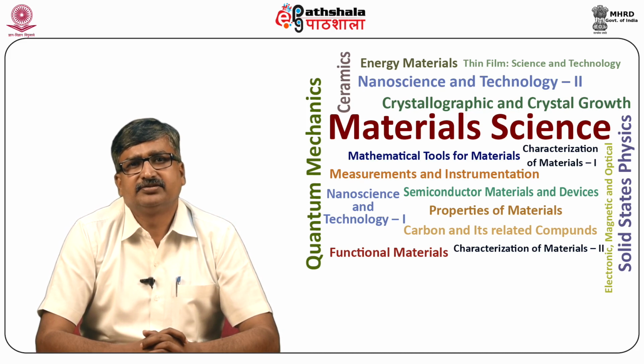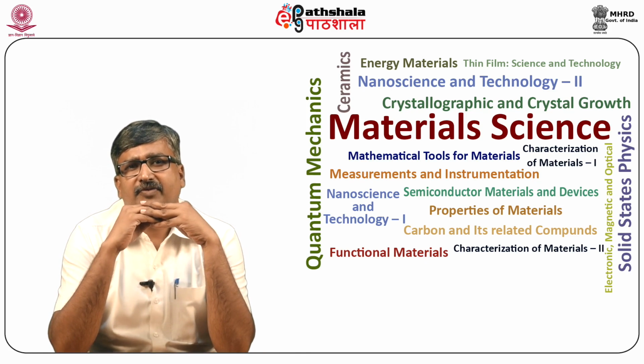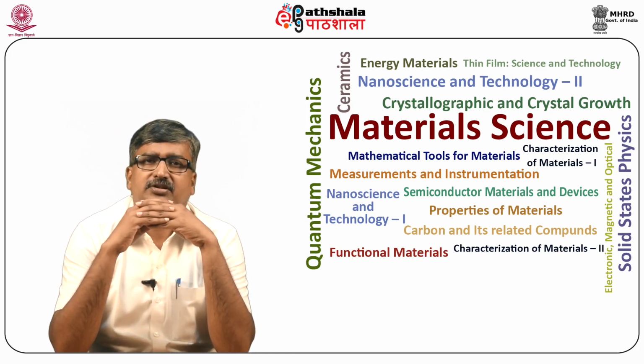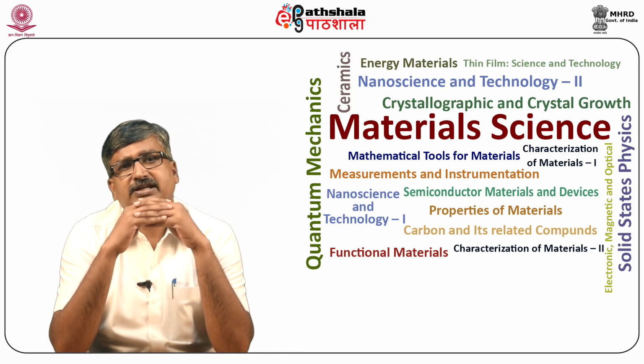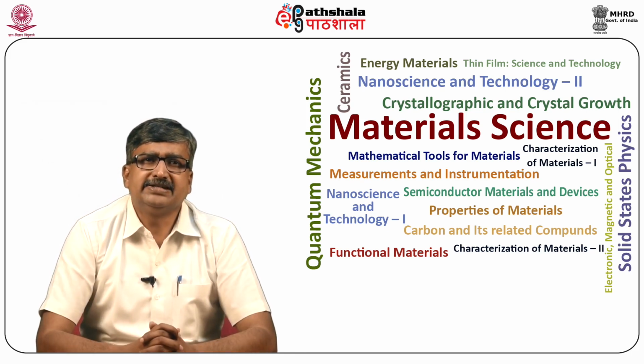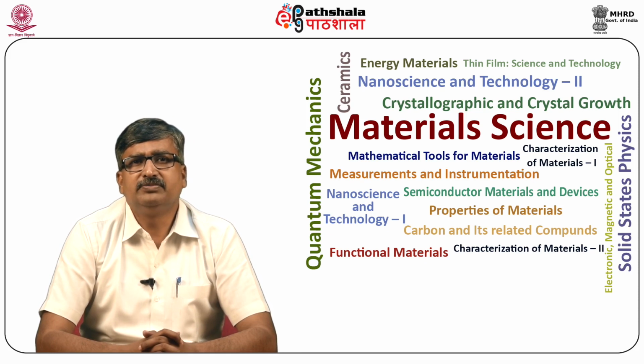It has been proven that continuous and smooth fibers cannot be obtained at very low viscosity, whereas very high viscosity results in hard ejection of the jet from the solution. Namely, there is a requirement of suitable viscosity for electrospinning. SEM images of the electrospun PAN product with different solution viscosities by adjusting the concentration of the polymer solution.